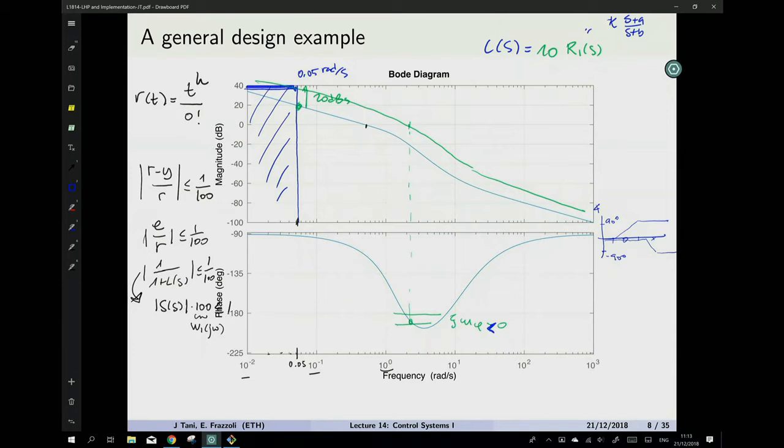around a specific frequency, which in this case is, say 0, this is 1, around this point, around 2 radians per second, okay? So the crossover frequency is 2 radians per second, and we want to increase our phase margin by 45 degrees. Now we need to choose a lead compensator to achieve that. It's basically about choosing the A and the B.